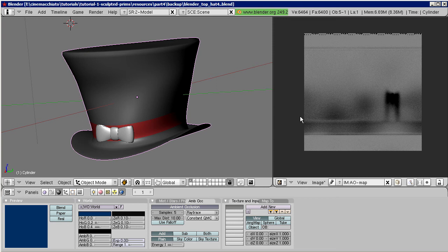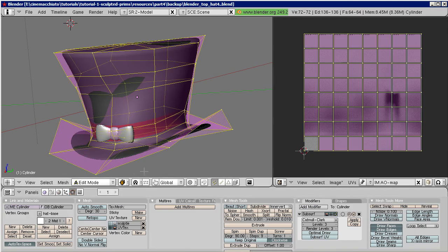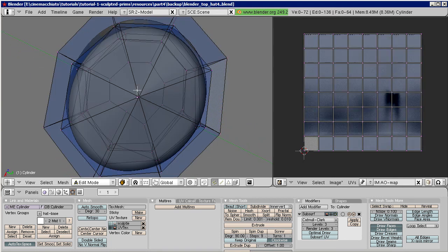So let us first take care of the triangles. Go to Edit Mode, switch to the Edit button section. Locate the pole, and select its vertices. You can look at the top menu bar to see how many vertices, edges, and faces you currently have selected. There should be 8 vertices in the current selection. Then switch to the Edit buttons, and click the Smooth button once.